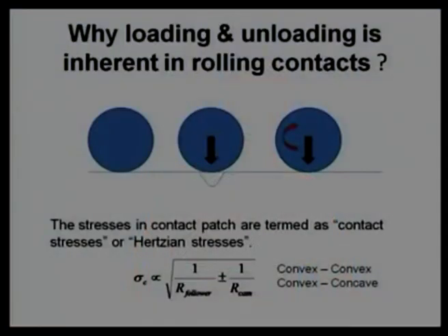And again, as the roller passes that point, it comes back from 10x to 5x and from 5x to 1x and 1x to 0x. So, whatever we do, rolling contacts are going to give us dynamic load. This kind of interface is always going to give us variation in stress, maybe from 0 to maximum compressive stress, and that is going to introduce some sort of shear force in a surface.